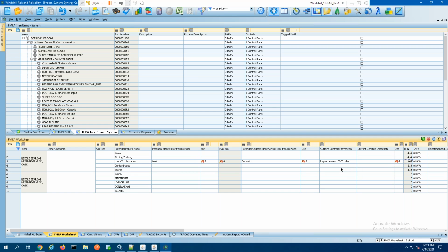And then, when you perform this FMEA from a bottom-up approach for the entire product, the car for example, you can then start to rank by the highest RPN numbers to make sure that those ones are effectively mitigated and controlled throughout the entire design cycle.